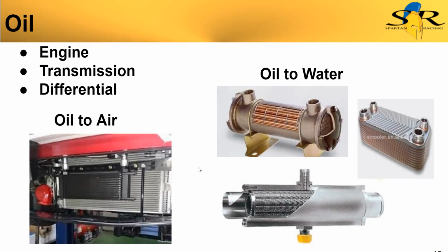I don't know that there would be much gain in performance from pumping, because if you're just running the oil through the air cooler, you're pumping the oil all the way up to the front, versus having an intermediate step where you're pumping the oil to the water, and then pumping the water up to the front of the car.